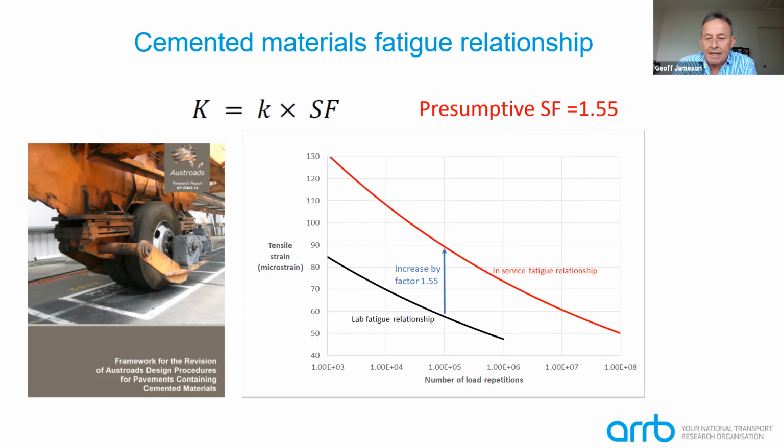So you can see for a given strain, the in-service fatigue life is about a factor of 100 greater than you'd measure in the lab for the same strain. So a big difference in how you translate strains to allowable loading in the lab versus the field.